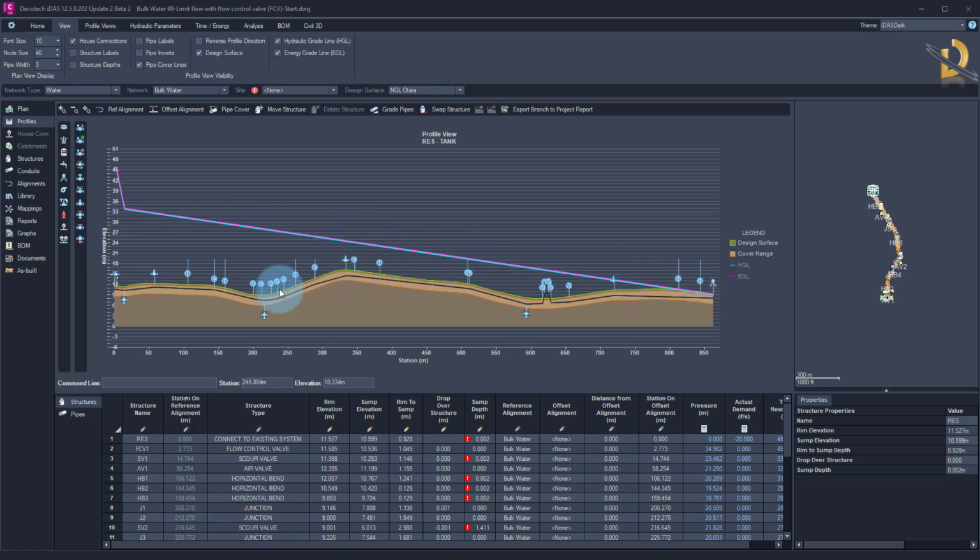If the surface had a hill here, I would have a problem because I would have a negative pressure at this area. So in this case, you're dropping the pressure throughout the system. And in some cases, that's what you desire to do. In some cases, you don't want that. So let's explore another option where we will add flow control valve at the end of the system. Just remember this shape so that it goes down and then towards the tank.